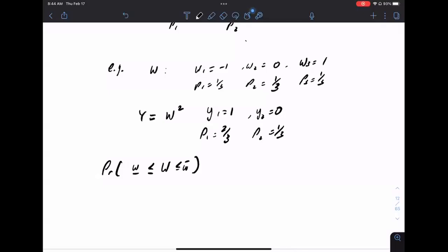So the way to read this probability is the probability of the wind speed is between these two numbers. The reason we care about this is that your turbine will have a cut-in speed and a cut-out speed, right? So often we want to understand how long, what are the probabilities your turbine is actually off, where your turbine is actually operating, generating power. So very, very often we compute this kind of thing. Right, so we're very interested in this probability as well.